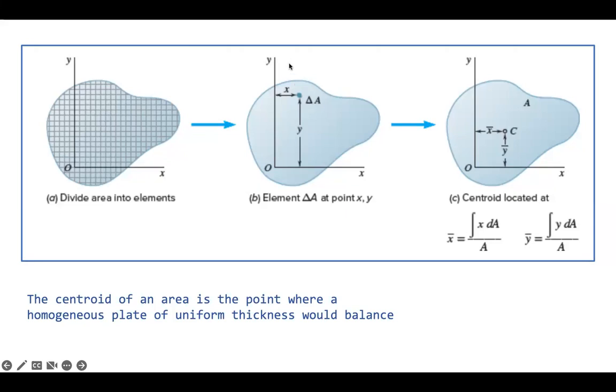So when you turn this plate around the y-axis, you want to have this distance over here, because this differential element you're rotating about the y-axis, but the horizontal distance to that point is x. Similarly, when we're rotating something about the x-axis, we're taking the y distance, so we're going to use y in that case. So back to the slide we were talking about previously.